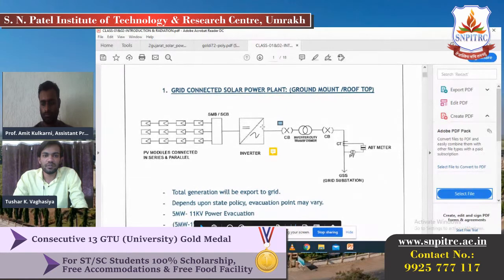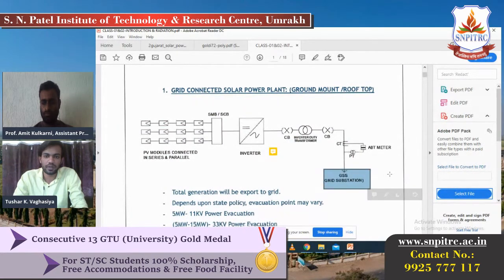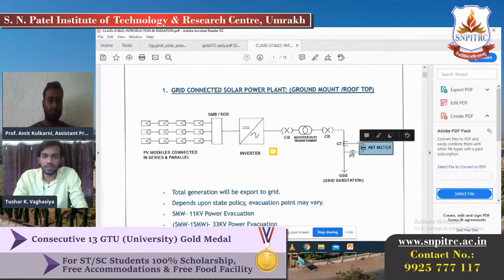So here the voltage is generated, and there are some other frequencies. Here is the grid substation, the existing substation of any particular government substation. We have to match the frequency as well as the voltage level, so we are using the inverter duty transformer. The CT and PT are for metering as well as protection, and the ABT meter is used to count how many units are generated from the solar power plant.